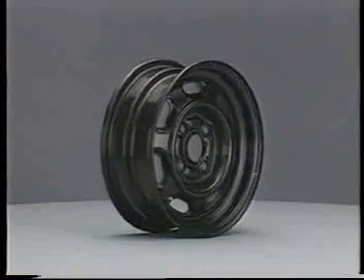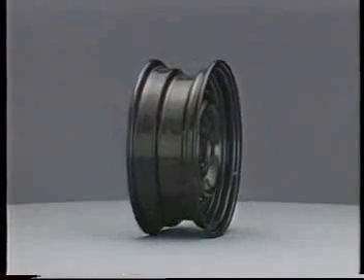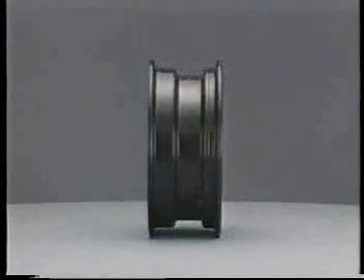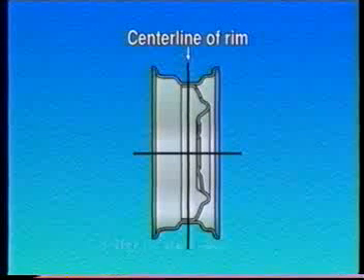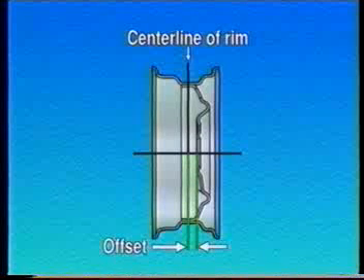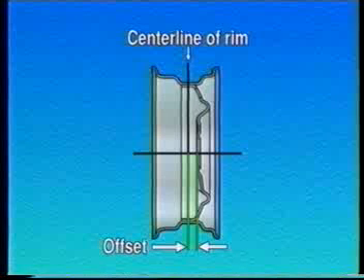Other precautions which should be taken in the size of the disc wheel are the offset and PCD. The offset is the distance between the center line of the disc and the surface which is fitted to the axle hub. Using disc wheels of different offsets would cause a number of problems arising from changes in the vehicle's tread or the tires coming into contact with the brake caliper.